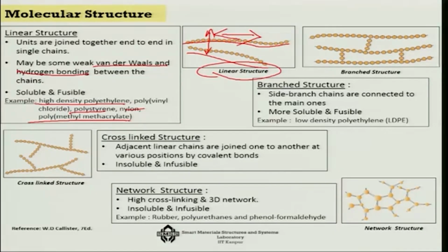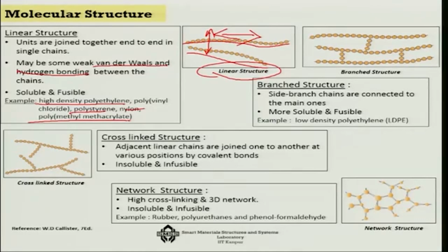The other point is that linear structures also generally have a good crystal structure, okay. Because their repeatability is generally very good, many of the linear structures, not all but many of them, are highly crystalline. So, if the degree of crystallinity increases, that also improves the mechanical property of the system. Now, some of the linear structures are not just linear, but branched type of structures.